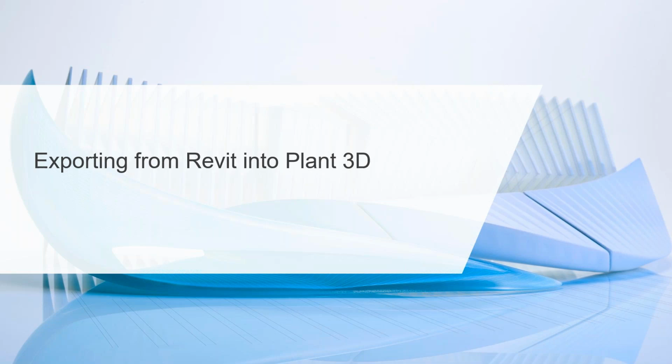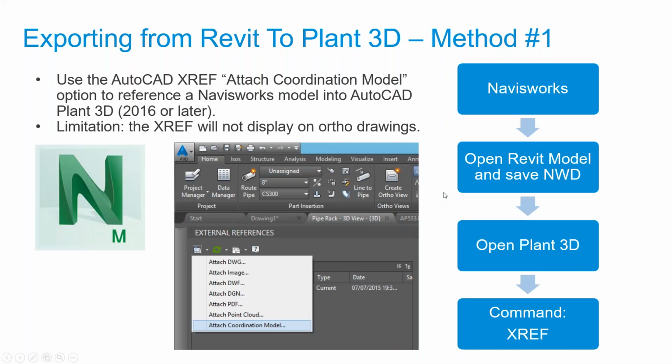Why would method 2 be an advantage? The main reason method 2 is advantageous is that the Revit views work better and they'll section the model properly. Method 1 doesn't section appropriately because it's just a reference. I hope that answers it. Okay, so moving on. Thanks, Jonathan. Appreciate the confirmation.